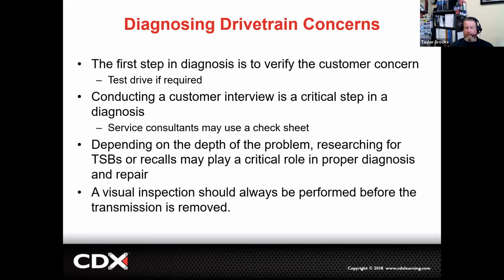For all of these different complaints, you're going to have to test drive the vehicle. As I brought up before, we don't have the luxury of being able to look at diagnostic trouble codes with manual transmissions to get us in the realm of possibility. Instead, we're having to rely on a test drive, and have an understanding of our expertise and the critical steps it takes to diagnose it.